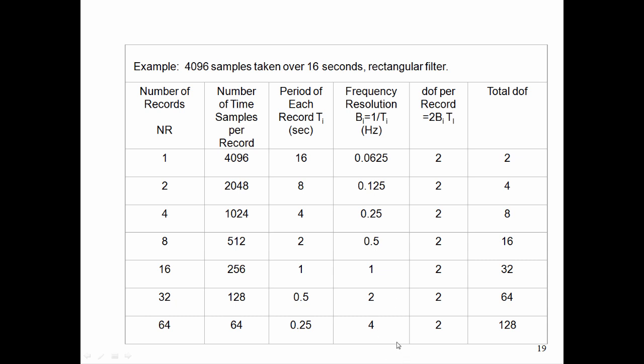And if that happened during a shaker table test, then that data would go to a quality control person who may or may not understand the finer points of random vibration testing, and it might cause some unnecessary consternation or some waivers or some paperwork. And we want to avoid extra paperwork, extra consternation, and we just want to show a nice, happy, smooth PSD plot for a shaker table test to show compliance for our specification.